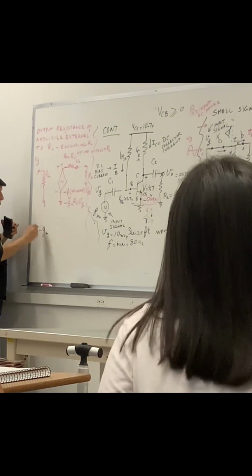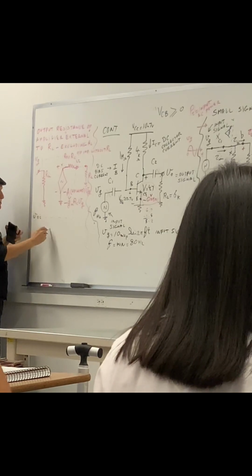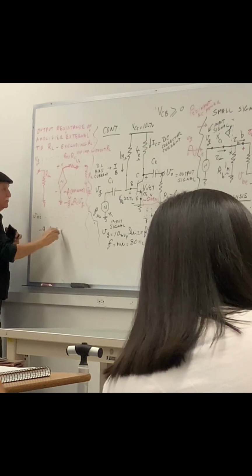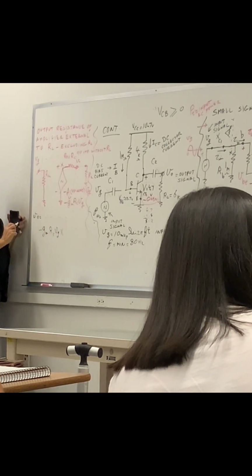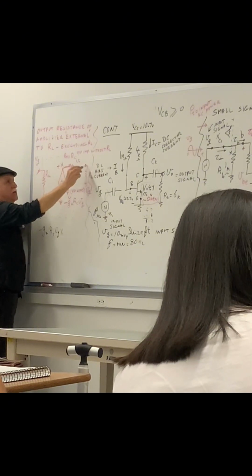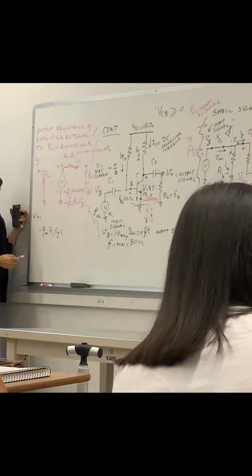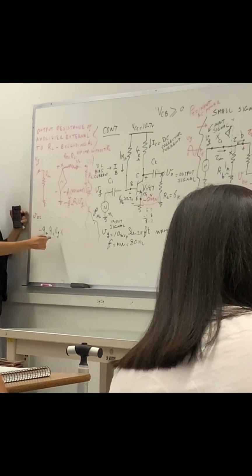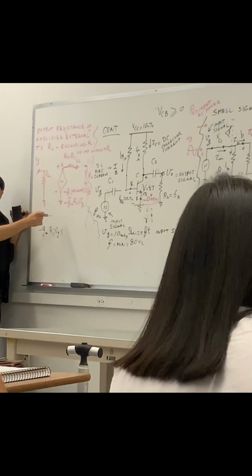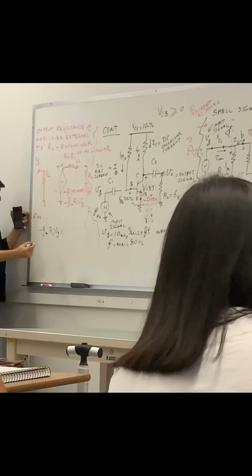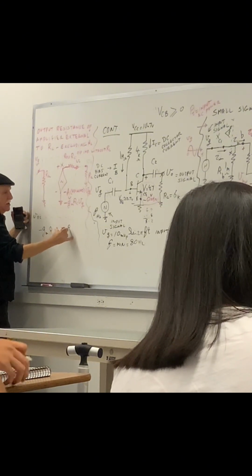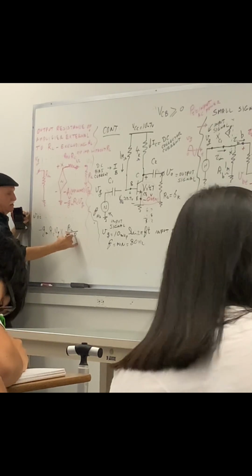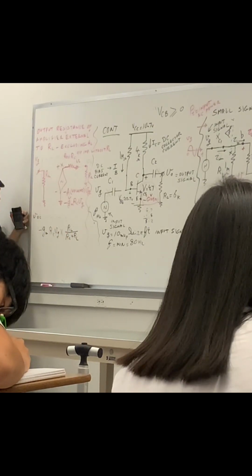Minus GM, so VO is equal to minus GM RC VG times. That's the voltage here, internal. When you join, this node becomes VO. So what is the voltage at the VO if this is known to be that much? Voltage divider. You see that? It's a voltage divider. Let me write the voltage divider. It will be RL over RC plus RL, because RO is equal to RC.